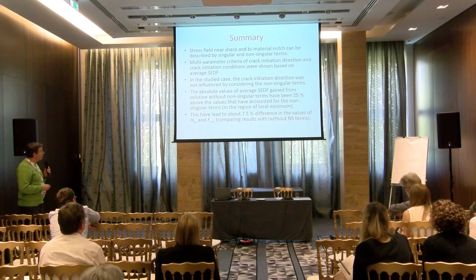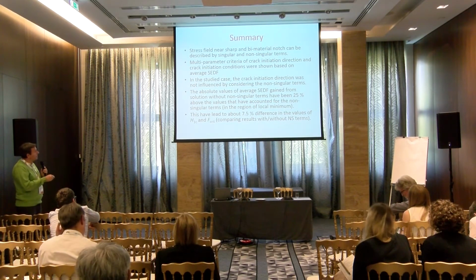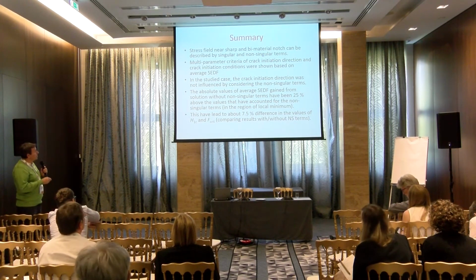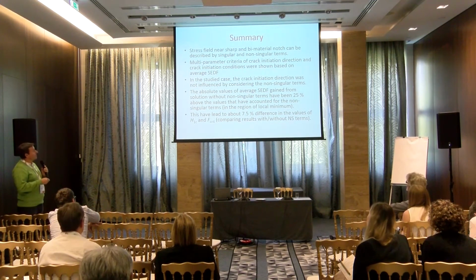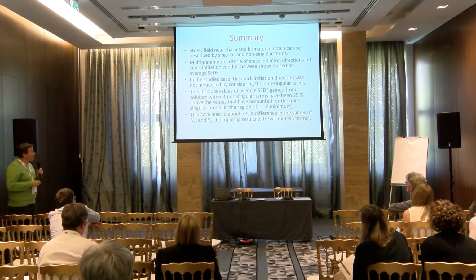So let me conclude. I have shown the stress field near the bimaterial notch tip described by singular and non-singular terms. Also the multi-parameter SEDF criterion was shown.